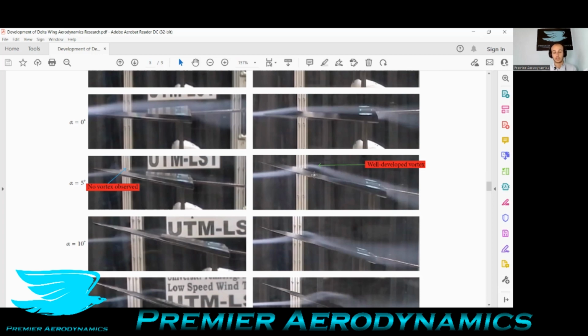So that's true. The strength of a leading edge vortex when you have a delta wing or any swept leading edge does decrease with increasing sweep angle. I've actually done quite a bit of research on this with some other flow control devices, and it's really cool. If you have one side which is not as steep as the other side, the side that's not as steep will have a stronger vortex and usually a bigger one as well than the one with a steeper angle. So you can get this imbalance as well.